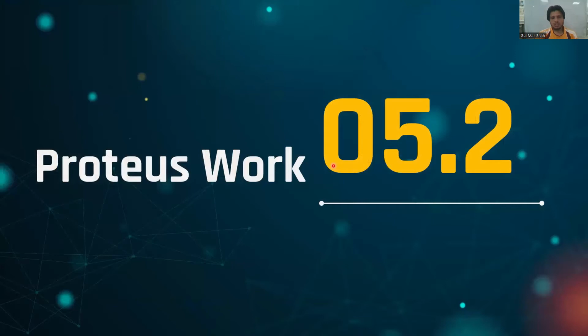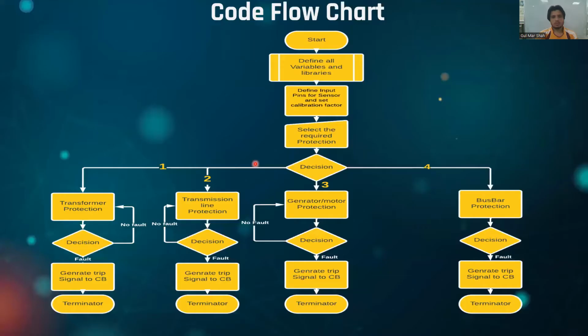Now, after the simulation in MATLAB, we have come to the Proteus work in order to see this behavior. This is the code flow chart where we define variables in libraries, and then define input pins for the current sensor in Arduino, and then select the required protection with the help of the keypad.